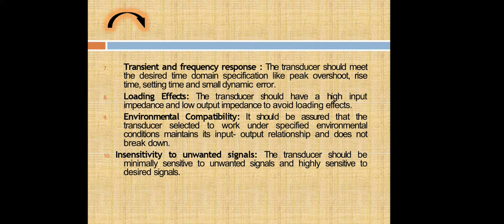Loading effects: the transducer should have a high input impedance and low output impedance to avoid loading effects. Environmental compatibility: the selected transducer should work under specified environmental conditions, maintain its input and output relationship, and not break down. Insensitivity to unwanted signals: the transducer should be minimally sensitive to unwanted signals and highly sensitive to desired signals.